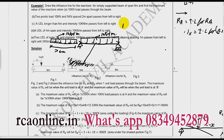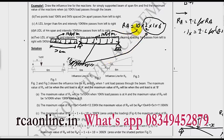So RA will be 10 into half into 1 into 6. What is half into 1 into 6? Area of this triangle. And 10 is the intensity of this UDL. So we get 30 kilonewton meter.